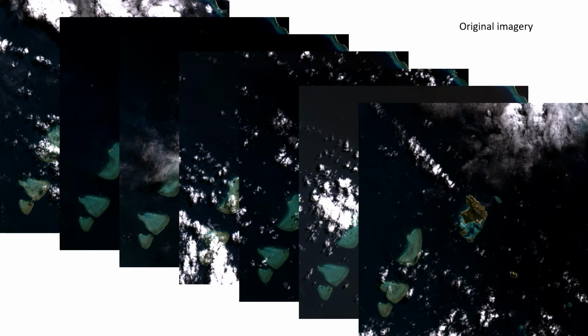FAB downloads all the imagery from the relevant MGRS tile, including lots of imagery that is partially but not fully cloud covered. The idea is that each image has information that can contribute to estimate bathymetry for some pixels, and except in extreme cases, all pixels are cloud-free in some images. So if we combine the information on all images in an intelligent way, we should be able to get a good estimate of bathymetry for the entire area.